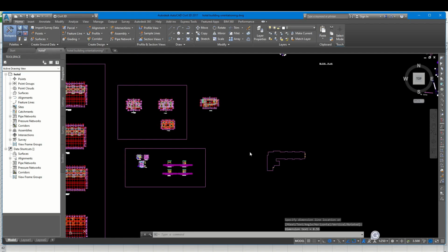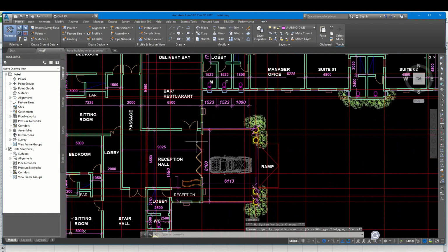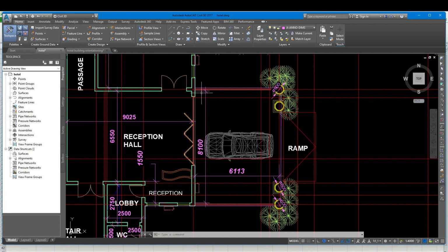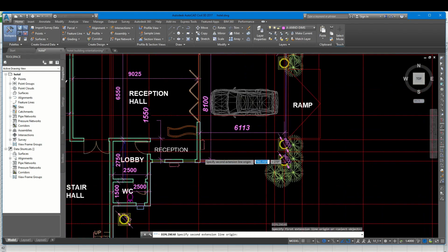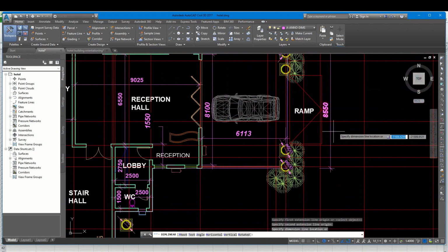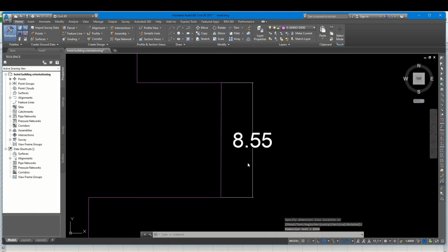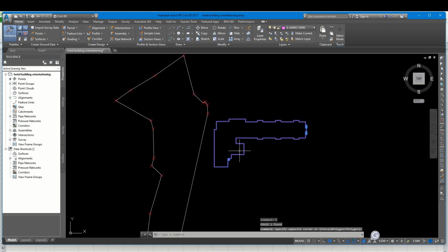Let's see what we have. Yeah, it's not too clear, so it's showing 8.1, but I will take the measurement from this close end, adding the walls, wall 1 to wall 2 external, and it's giving me that 8.5, which shows that it is an accurate one. Now I want to take the building block and orientate it into the site.